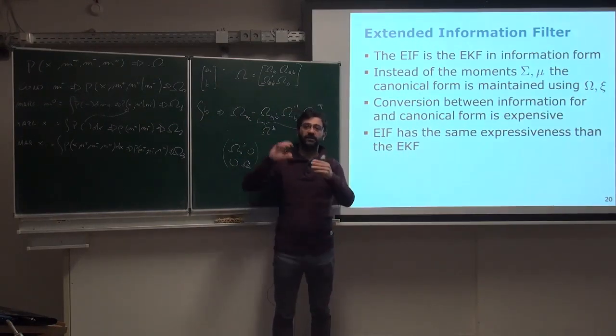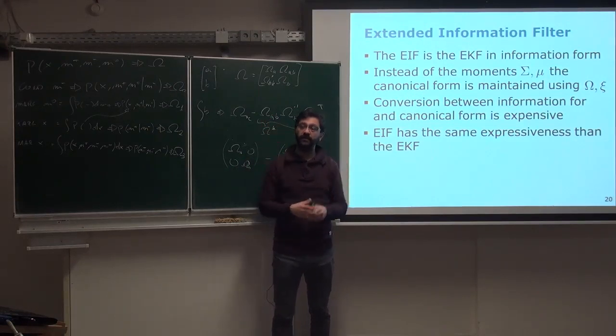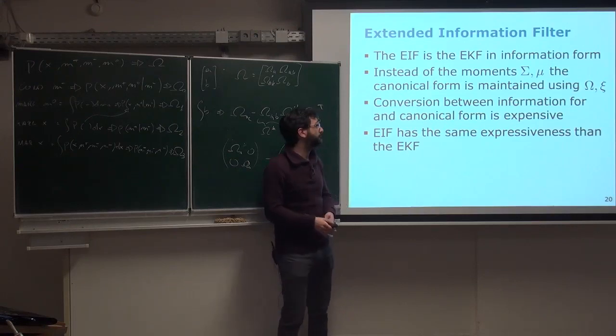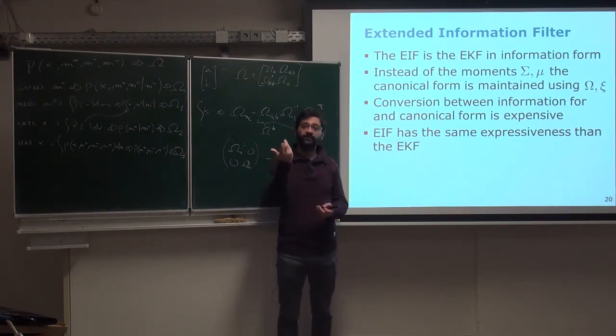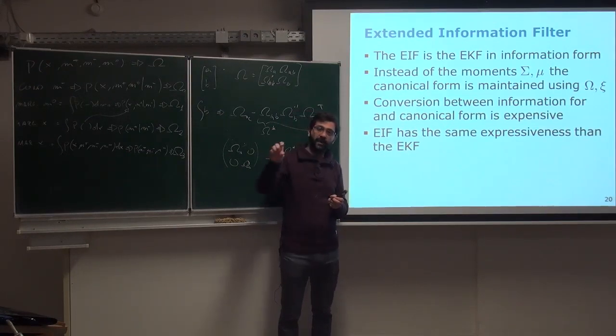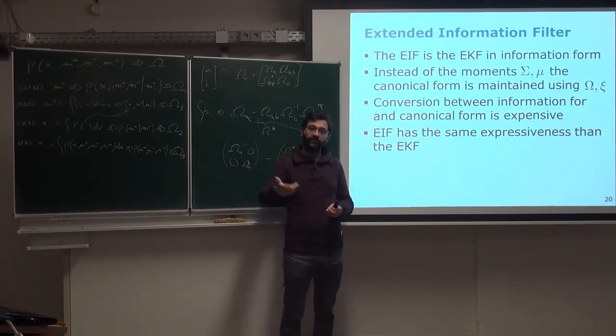It's just that the two steps, predict and update, change the complexity between each other. The predict step becomes more expensive in an information filter, while the update step becomes easier. You can still use the same trick of the inversion lemma for the information filter, so you can still exploit this low rank update of your information matrix during an update of the system.